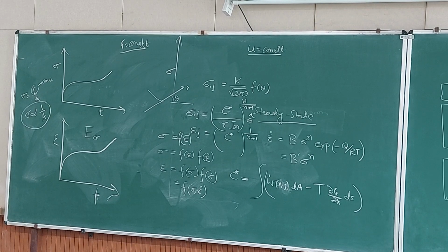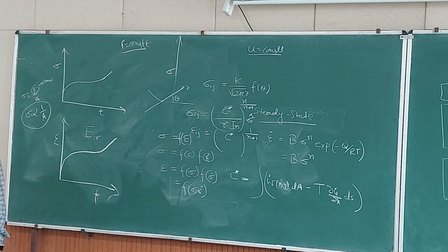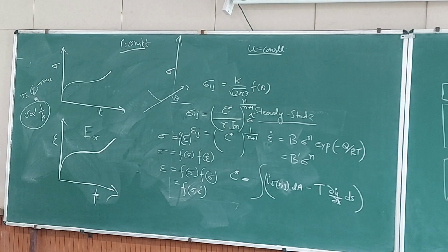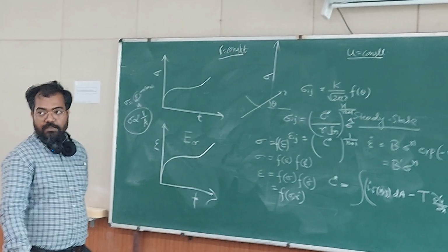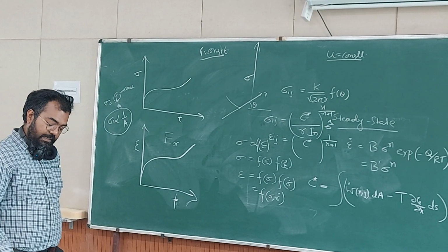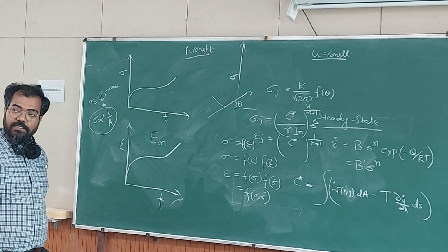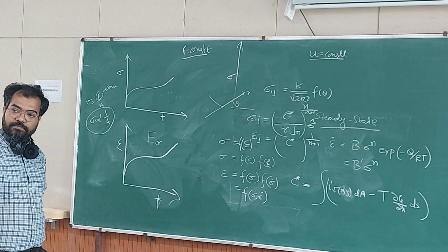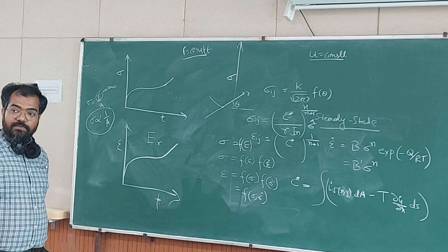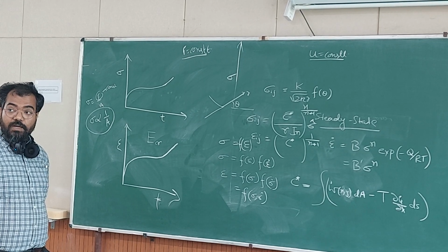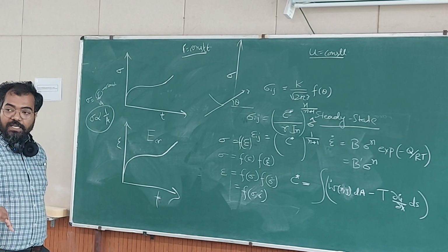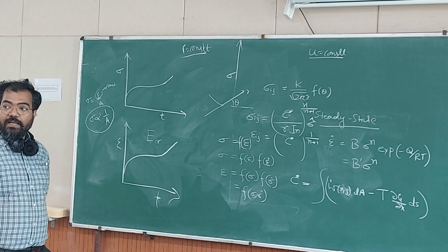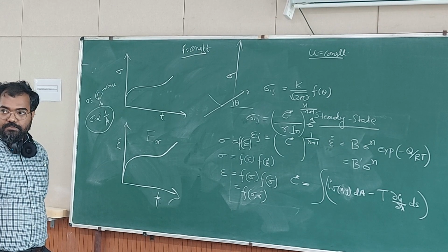J is defining stress and strain when deformation is plastic, not time dependent. And K is defining stress and strain when things are elastically deformed. Right? But apart from that, K is describing how much stress is getting intensified. J is defining also, apart from defining the stress and strain, it is also defining that how much energy is released per unit crack length. Right?